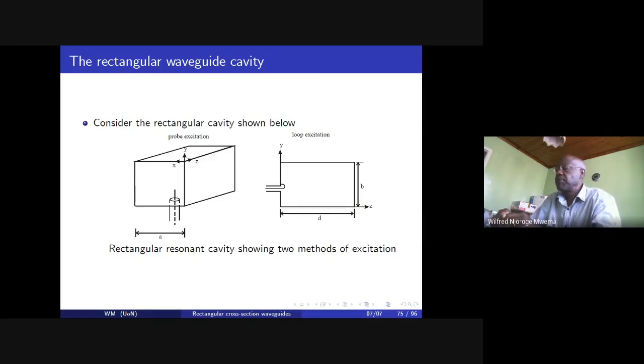That is, if we were to make an LC tank circuit, we expect that its impedance at resonance is infinite, but it's rarely infinite because the coil will have a coil resistance, the capacitor may have a shunt conductance as well, and this will add up and give a residual impedance. It could be high, but not infinite as expected.